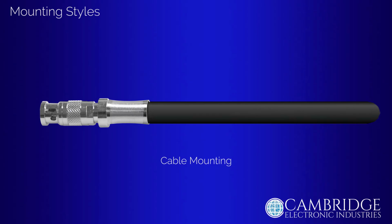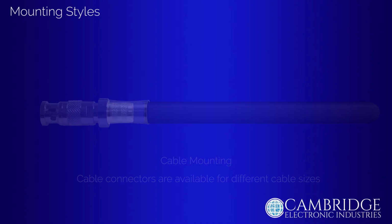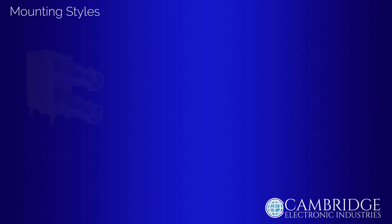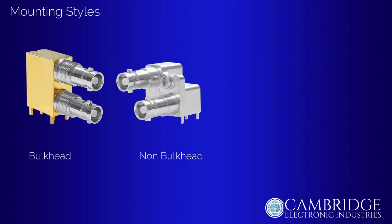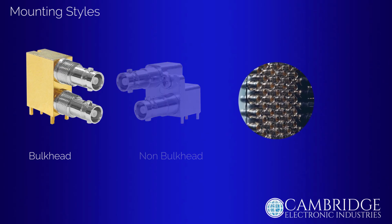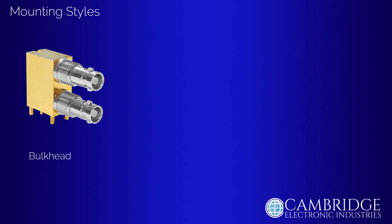Even though the interface of a cable connector is standard, the cable entry size differs depending on the cable type that the connector is designed for. Coaxial connectors are available with a bulkhead or as a straight connector style. A bulkhead is a partition or wall, and in electronics this usually refers to the equipment enclosure or panel.